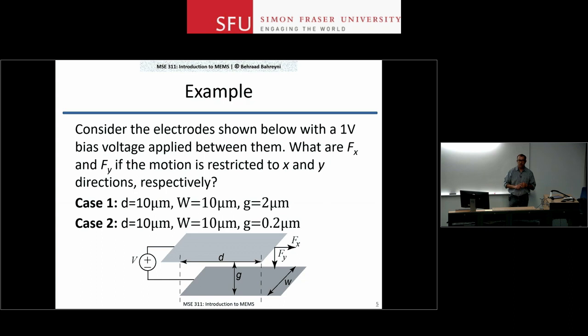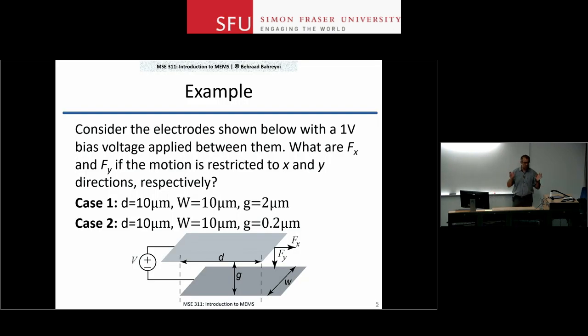And that is one of the reasons that DRIE is so popular in microsystems technologies. The first reason is that you get these nice sidewalls that make your device well structured and well behaved, but you also have the ability to create these narrow gaps that can go very deep into your structure.